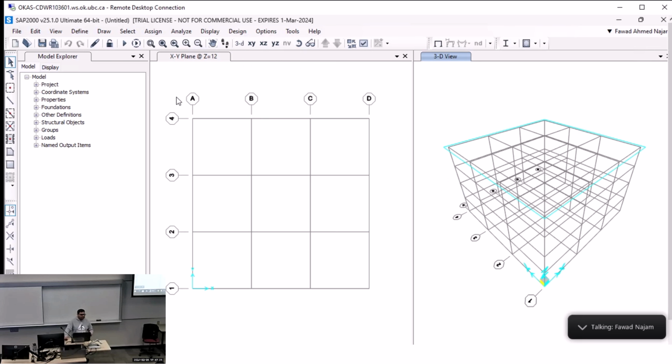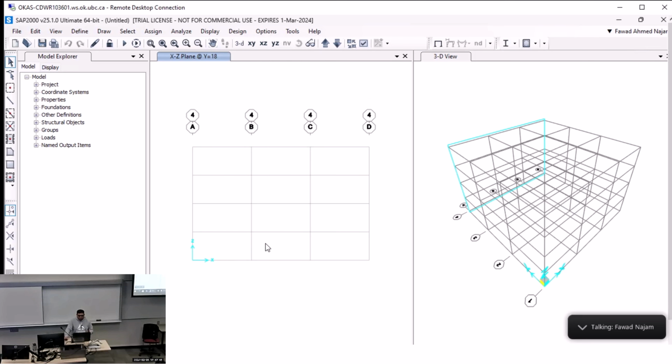So, let me just again click on 3D and it will restore to the default 3D view, which is the default isometric view, right. If I click somewhere on the left hand side of the canvas, I will be on this tab now, and it is by default my xy plane. But if I want to see the xz plane, I can click here and now I can see the xz plane. So, where you are on the left hand side view, you can see it by this cyan color also on the right hand side, right.